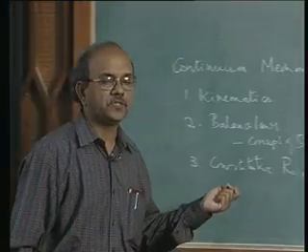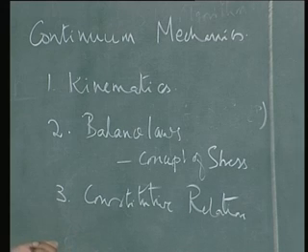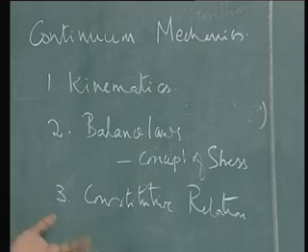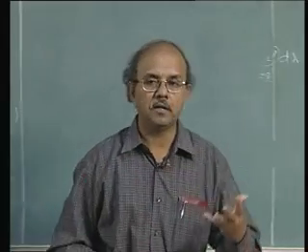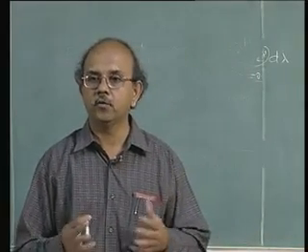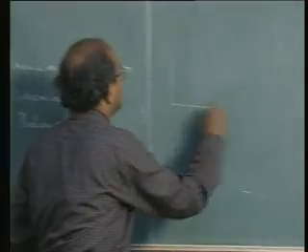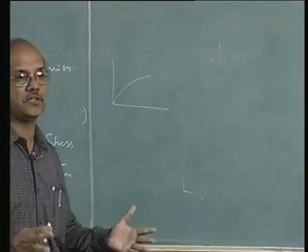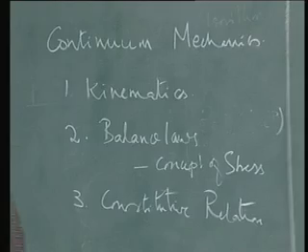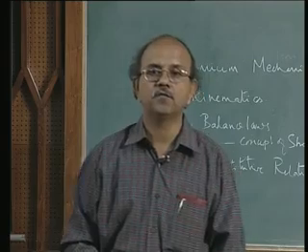One of the things which I want to state very clearly right now is that when we discuss constitutive relationships, though you know that it is a stress-strain relationship, they are not ones which result from a curve fitting of an experiment where you determine sigma and epsilon. It is not just curve fitting. In other words, you don't just take a sample, break it, and then plot a graph, stress versus strain, and say that this is the equation for this graph, and say that is the constitutive equation. No. Constitutive equations have deep theories which are covered by the science of thermodynamics.